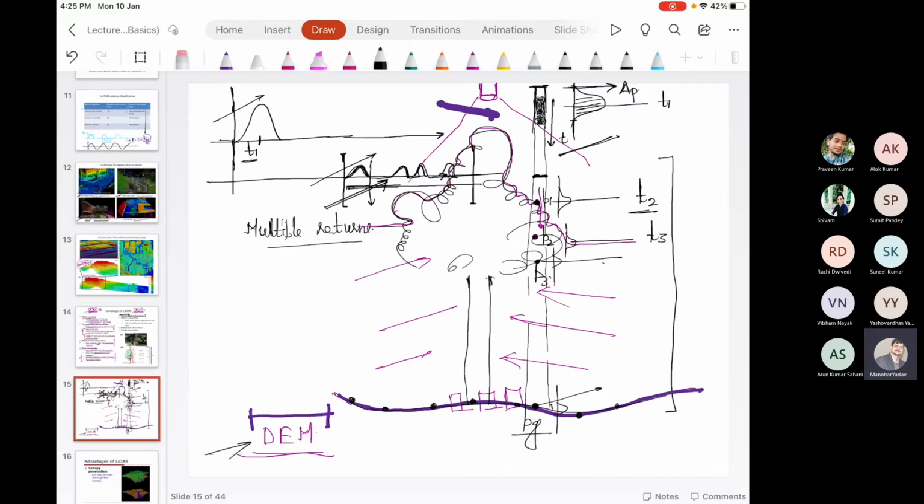So the water content will be responsible for the decrease in amplitude of the return. If I talk about the local maxima, this local maxima value will further decrease, and it will decrease to a level that the receiver can't identify due to its internal sensitivity.